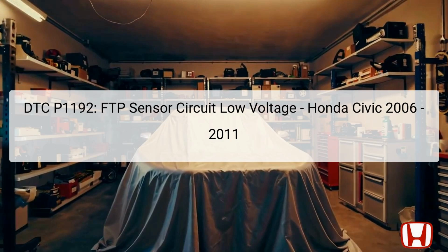It is essential to understand the role of the FTP sensor, notably its location, usually found near the fuel tank, where it measures fuel temperature and pressure to inform the ECM. This feedback helps in regulating fuel injection and combustion processes for efficiency and emissions control. Having the right diagnostic tools and data at hand is crucial before proceeding with troubleshooting. This guide will outline step-by-step procedures to diagnose and address issues related to DTC P1192 effectively.